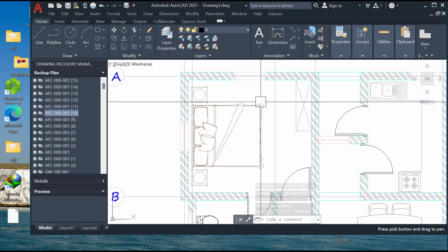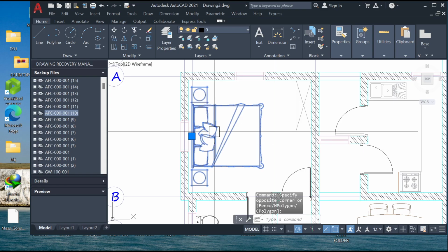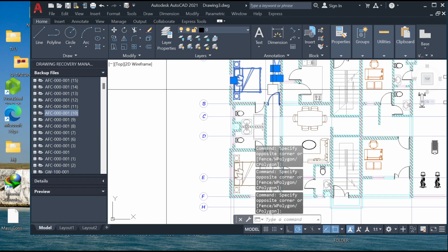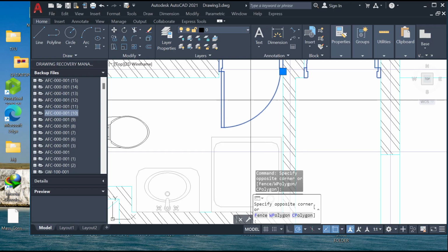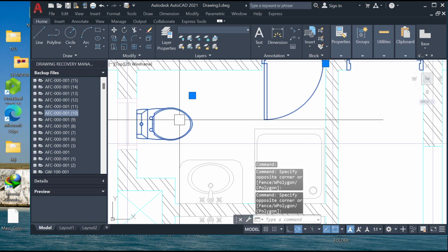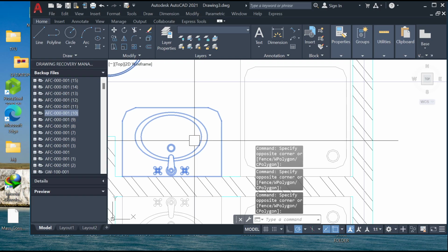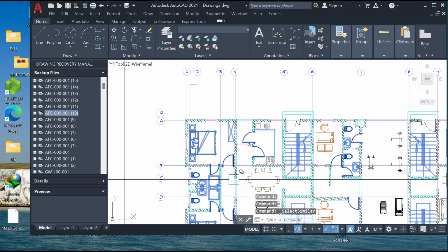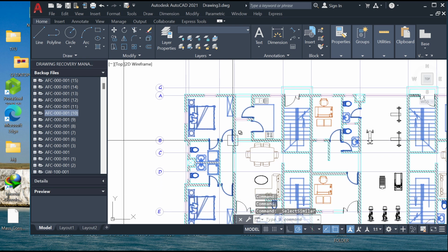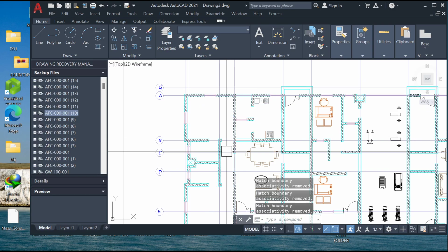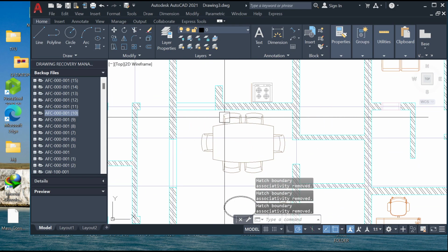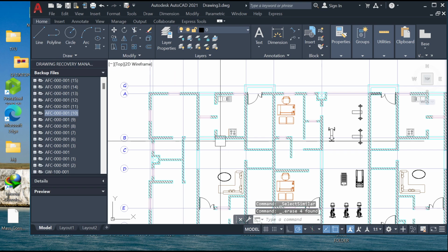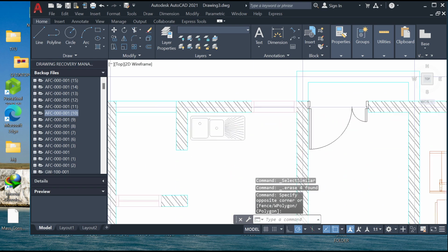The next thing is, all the symbols for the wardrobe, the doors, the wash hand basin, the kitchen cabinet and what have you are also not needed. A good general arrangement should be clean and very, very neat. We click on select similar, then we click on delete. Are we together? Then we have this also. Click on select similar and click on delete. These ones and these ones.